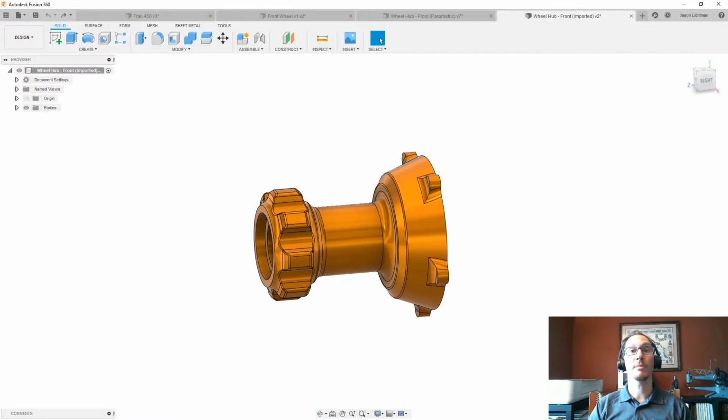Use that surface to maybe do a split body command to the solid, right? And then move on and continue doing other solid modeling techniques. So it can be a hybrid of solid and surface modeling, just like it could be a hybrid of history modeling or parametric modeling versus no history modeling, which is also called direct editing or direct modeling. So you guys just learned a whole lot of terms right there. But this hybrid, this base feature, allows you to be able to bridge both worlds really well. So let me give you an example.